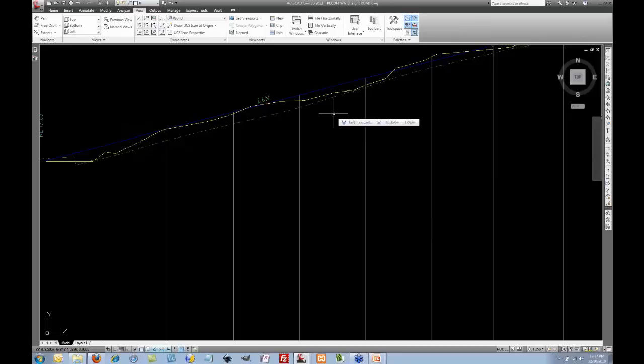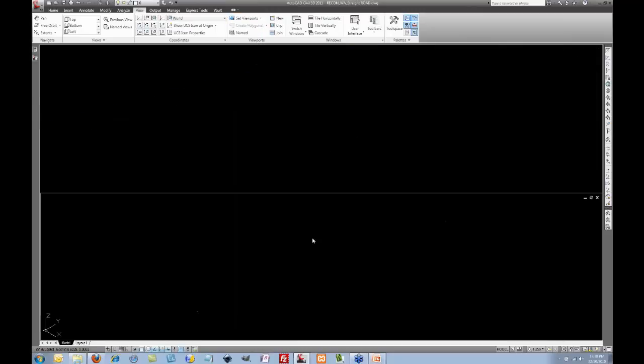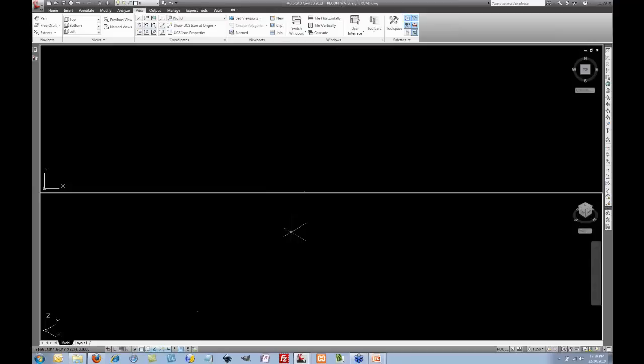Because it's the edges of buildings, you can see it's quite jagged, so we don't have the flexibility in this case to regrade it. They're heritage, so you can't touch them. So you basically have to make sure your crossfall corresponds to something similar. So I'm going to switch back to two viewports. What I do is show the cross-section updating as I move these.